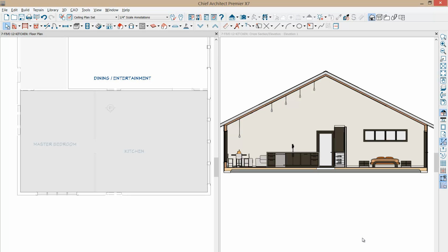The next thing I want to do is use my custom ceiling planes and draw in this area, right where my mouse is towards the dining room table or the breakfast table, a flat ceiling plane, and then extend the vault going up at a 5 and 12 pitch. When we built our roof, the roof is actually at a 6 and 12 pitch. By going at a 5 and 12 pitch, that will lower the overall ceiling height and allow us to get insulation into that area.